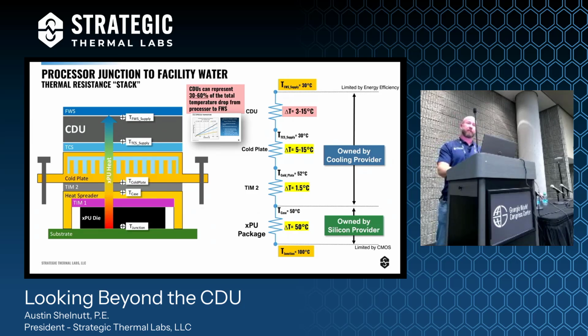So approach temperature of the CDU, in simplest terms, is the temperature drop between the water that comes out of the CDU to go to a cold plate to cool off the processor and the temperature of the water supplied by the building, right? And obviously we want to get those as close together as we possibly can, but I previously mentioned on our first slides, the only way to do that is to make your CDU extraordinarily large. There is a practical limitation on how big a CDU can be in a rack. It has costs, both capital expenses and in space that coincide with that. Also, making your CDU extraordinarily massive is somewhat antagonistic towards the densification process that most people have been trying to achieve for the last decade or so.